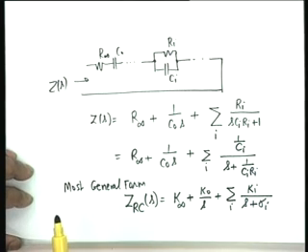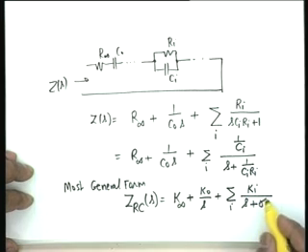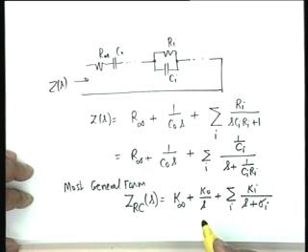One of the properties of an RC impedance is obvious now, that its poles must be on the negative real axis. There can be a pole at the origin and there can be poles at s equal to minus sigma i, where sigma i has to be positive.